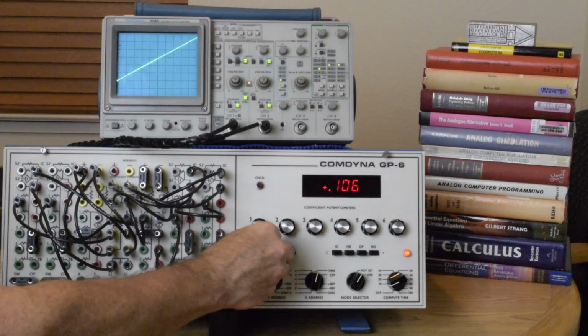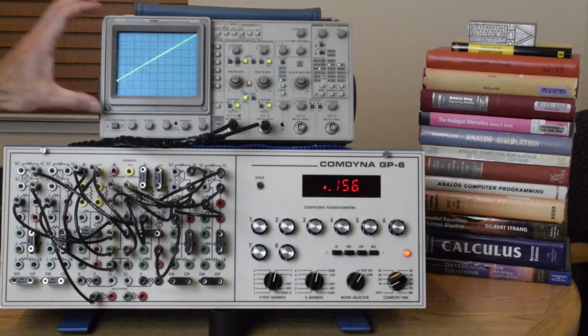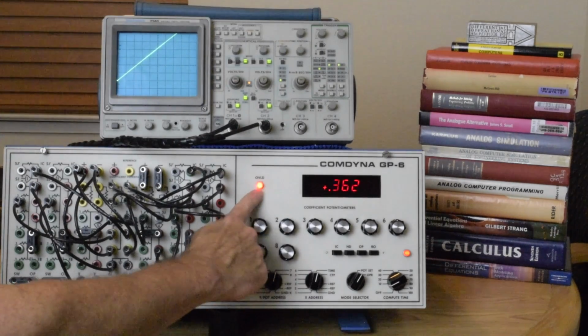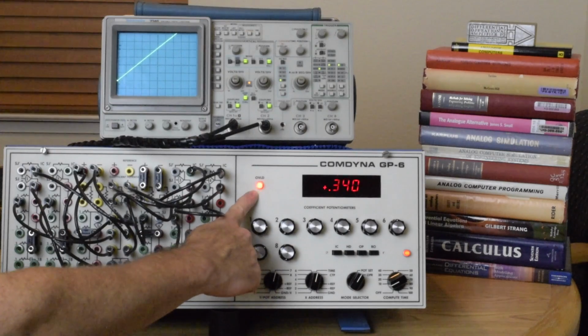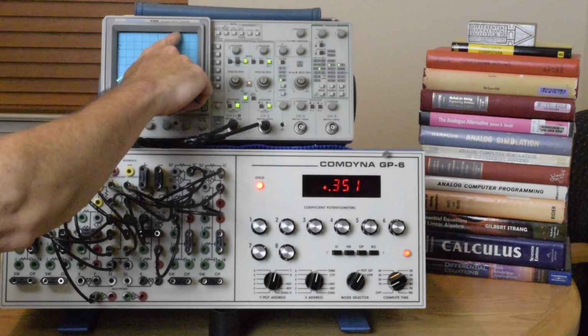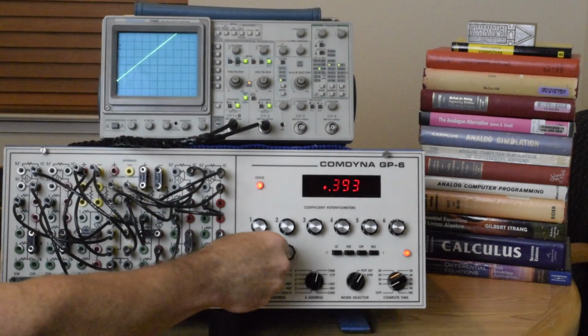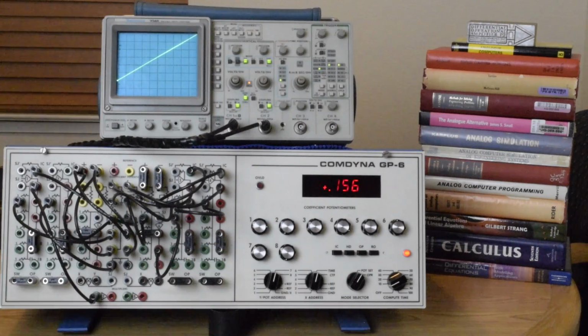Now, an interesting part of the analog computer is, as I mentioned, the reference voltages are from minus 10 to plus 10. If I increase the slope too far, you notice the overload light comes on, and that's because we're exceeding the maximum range of the analog computer. Now, at first glance, you might think that makes the analog computer somewhat limited in its use, because you would think it could only solve a problem with parameters from -10 to +10, but that's where scaling comes in.